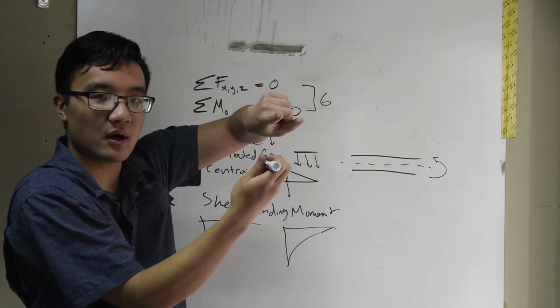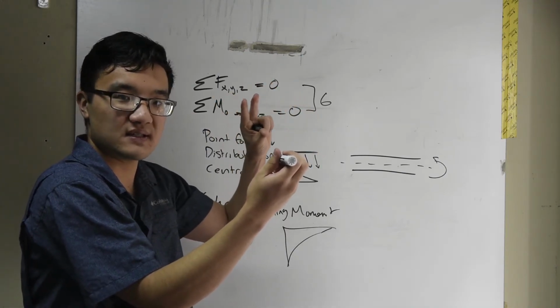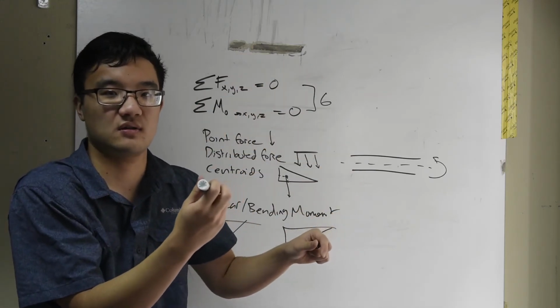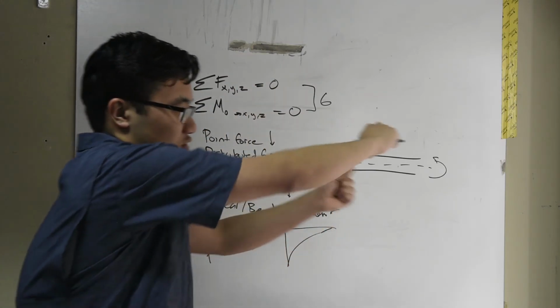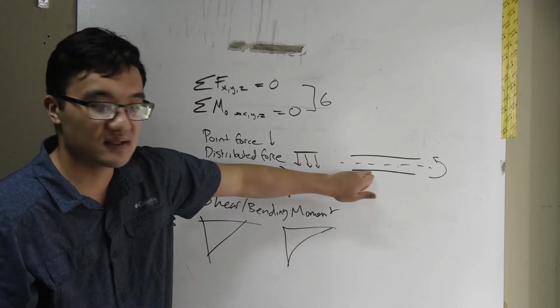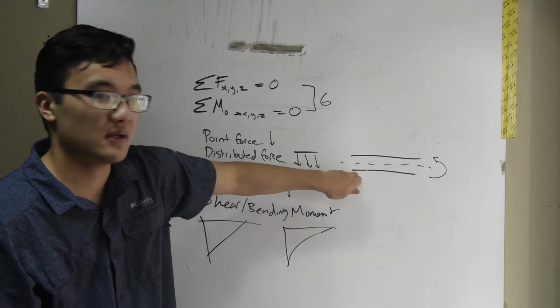But if I have 2 bars, then because they're fixed here, there's a little bit of a moment that's resisted in that direction. Not to mention that if you try to pull it in any other direction, you've got double the support. So this allows us to resist moments, right? That's why we made that choice.